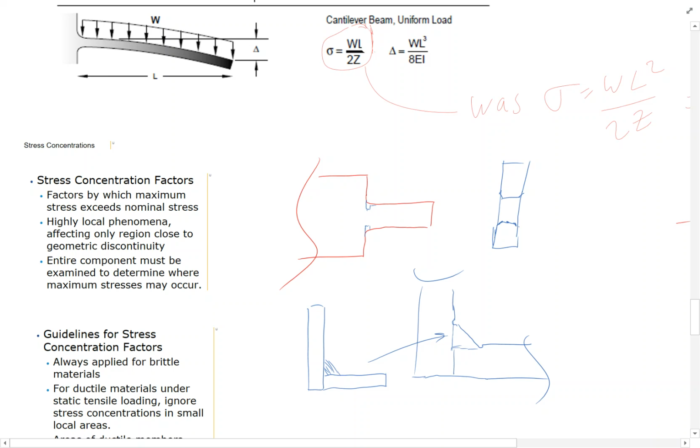What you're calculating is average stress. It's not maximum stress. And what stress concentration factors do is they don't increase the average stress on a structure. If I'm looking at this as a shaft with a turned down portion to it, and maybe this thing goes into here and gets loaded in some way, and I calculate what the stress will be in that shaft.